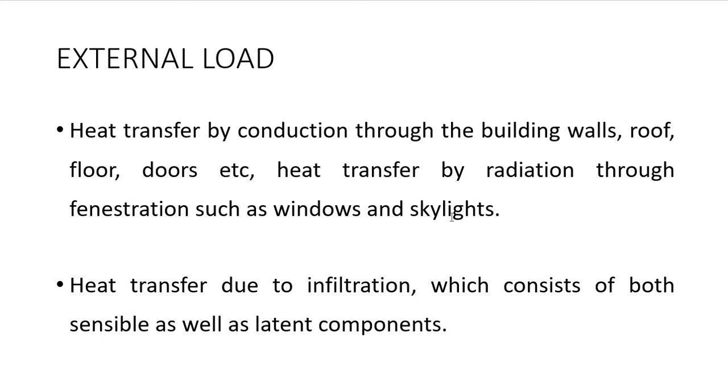Another one is heat transfer due to infiltration. Infiltration means the leakage of air into the room. So there is a chance that some amount of air will leak into the room from the surroundings. Sometimes in the case of a room, we may open and close the doors. So when we open the door, some air will come inside. That's the infiltration, the air leakage.